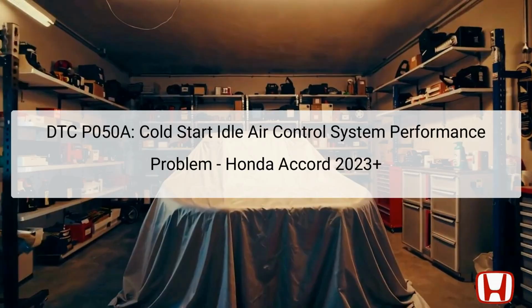DTC P050A indicates a cold start idle air control system performance problem in the Honda Accord 2023 model and beyond. This code is triggered when the Powertrain Control Module (PCM) detects an issue with the actual airflow being either insufficient or excessive compared to the target airflow during the Quick Warm-Up System (QWS) operation.